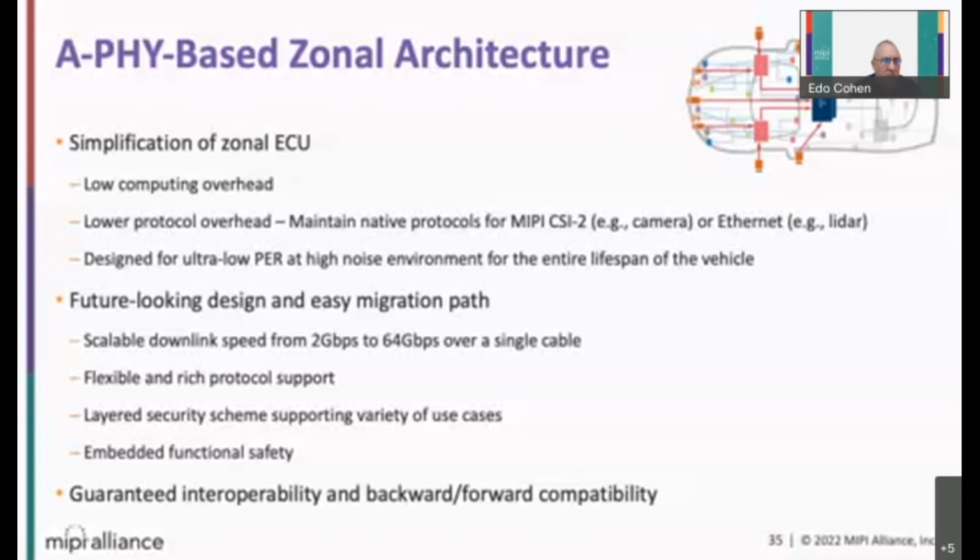MIPI Alliance held a very long session in independent labs to understand the impact of stress and aging on these cables, on the shielding effectiveness, and the impact on the noise penetration to the receiver. And A-PHY, in all generations from 1.0 to the next generation, is designed to meet these kinds of challenges for the entire lifespan of the vehicle.